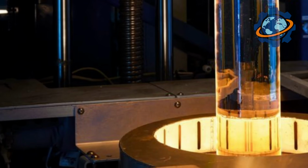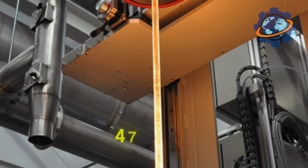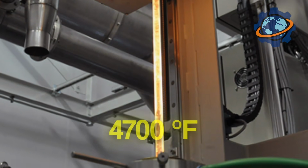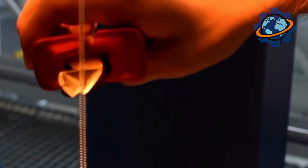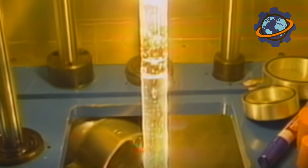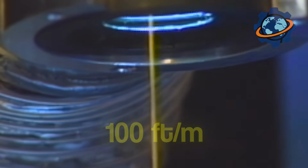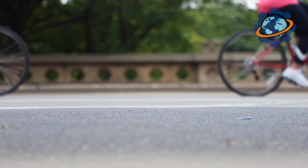The preform is placed in a special furnace that heats up very intensely. The temperature inside it reaches approximately 4,700 degrees Fahrenheit. This temperature is so high that the glass becomes soft and starts to melt, like caramel on a stove. When the end of the preform melts, a drop of molten glass begins to drip from it. This drop is very carefully drawn downwards, and a thin thread is formed from it. This thread, the optical fiber, is drawn at a speed of approximately 1,000 feet per minute. Imagine that. It's faster than a cyclist moving through the city.